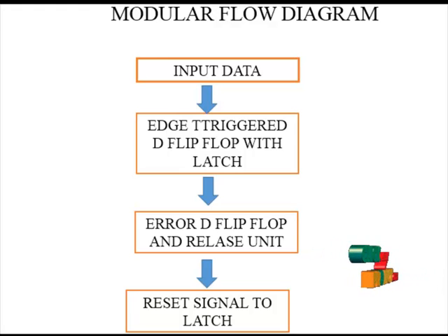The first XOR gate detects the difference and raises its output to high. The latch captures and holds this response. Thus the second XOR gate provides at its output Q the complement, and now the Q output of the EDC flip-flop carries the correct value, which feeds the subsequent logic stage for its computations. Consequently, the error is locally corrected.